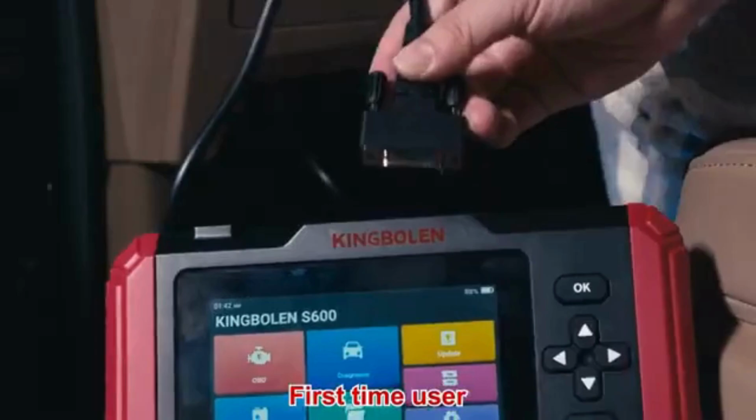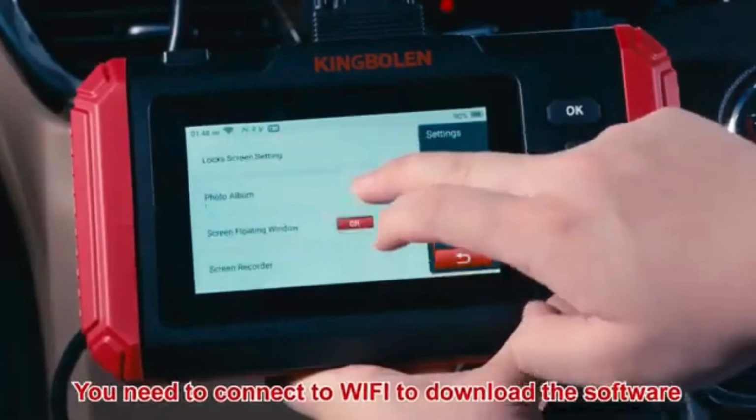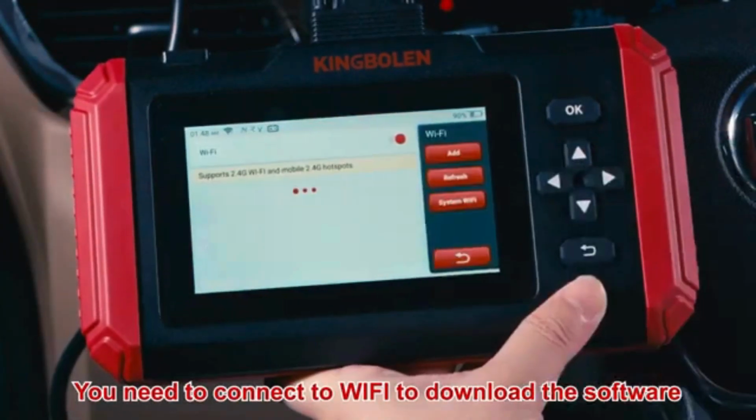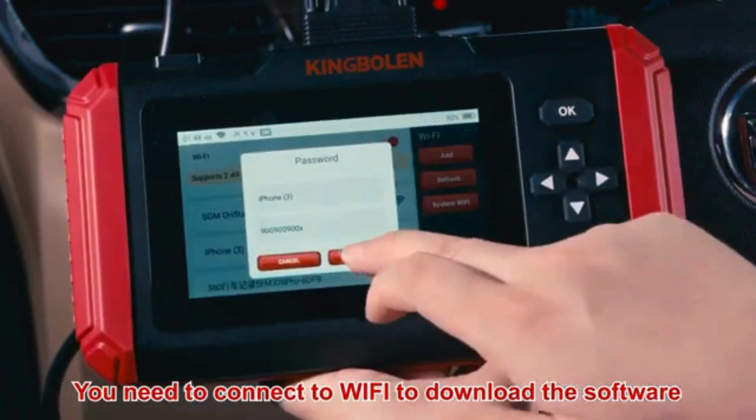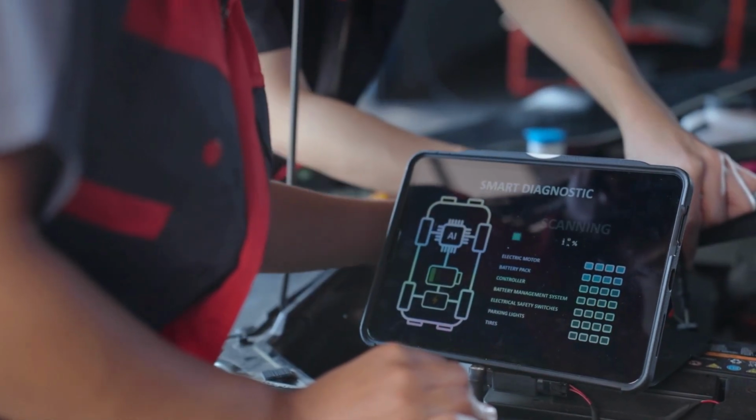Simply connect the scanner to your vehicle, follow the instructions to clear the trouble codes, and see if the P0062 code reappears. If the code comes back, it means there's a persistent issue that needs further troubleshooting.